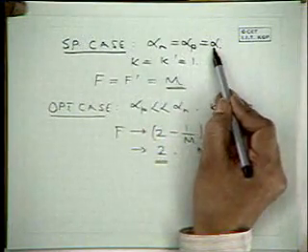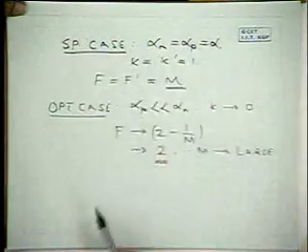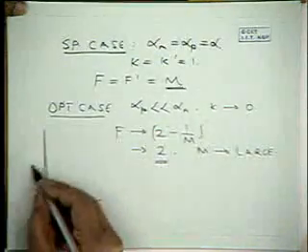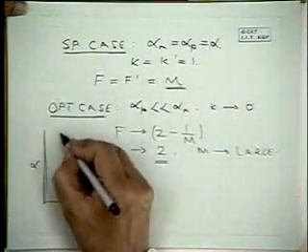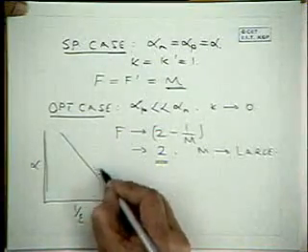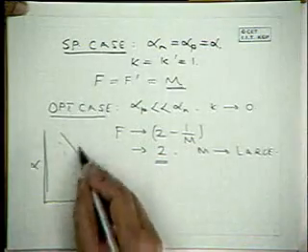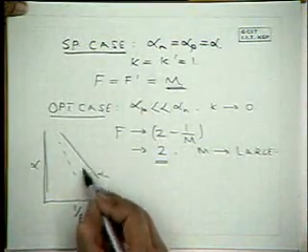So this is much better than the case where alpha p is equal to alpha n, equal to alpha. That's why right at the beginning, when we looked at those figures of alpha against 1 by E, I said it is better to have, and remember this is a log scale, alpha n much larger than alpha p.